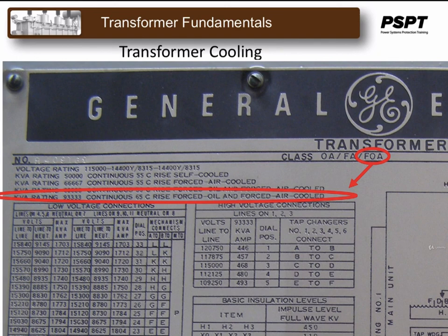The mechanical assisted equipment is usually automatically switched on as the operating temperature rises, but it could be operated manually. In either case, close observation is required, as this expensive equipment is operated close to its rating limits. In any event, protective relaying should take it out if the limits are exceeded for too long.